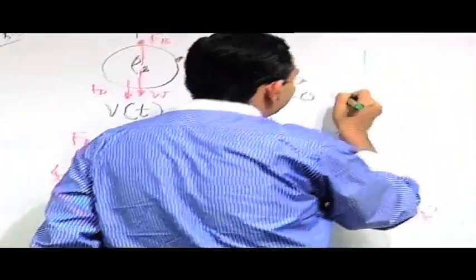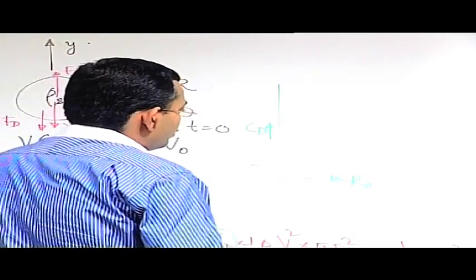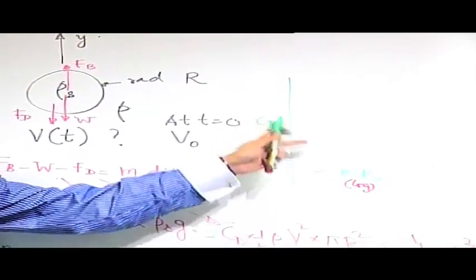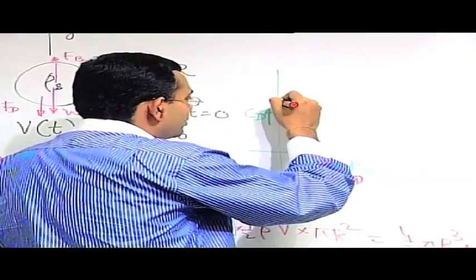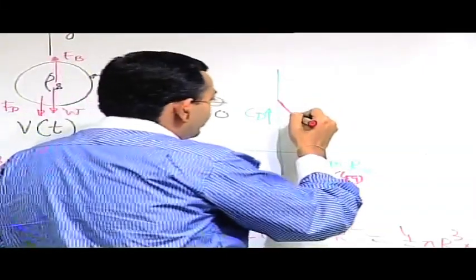So, if you draw say CD versus Reynolds number for flow past a sphere, what you get is something approximately like this. Let us say we plot with a log of Reynolds number. CD equal to 24 by Reynolds number, if you plot it as a log of Reynolds number, will be like a straight line, but that is valid only for very low Reynolds number. Then there is a significant deviation from this, and so it will come down like this.